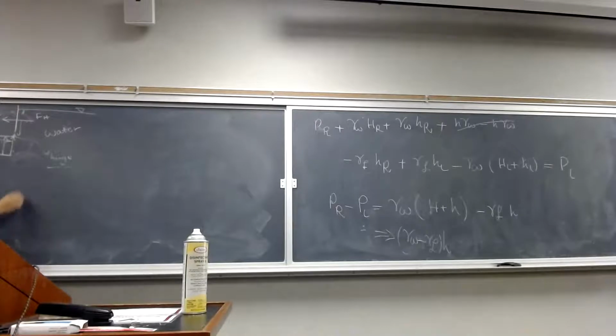Pressure is not going to increase or decrease, and it's going to be equal to gamma of water multiplied by this H. So at this depth, your pressure is going to be gamma H, which is going to remain constant throughout this horizontal plate. So gamma H. How can we calculate this F of V, the vertical force? Gamma H multiplied by your area.